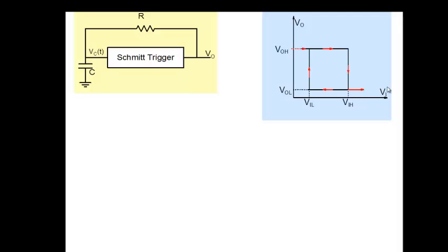So far it just looks like an inverter. It starts from a high value, and at a certain threshold value it switches to a low value. But what is very interesting is that normally, if you have a simple inverter, when you reverse the input voltage, normal inverters would come back and follow this particular line here. In this case, it doesn't. What happens is it comes here, and at this value, it doesn't go up. It remains low till you reach another threshold value, which we call VIL.